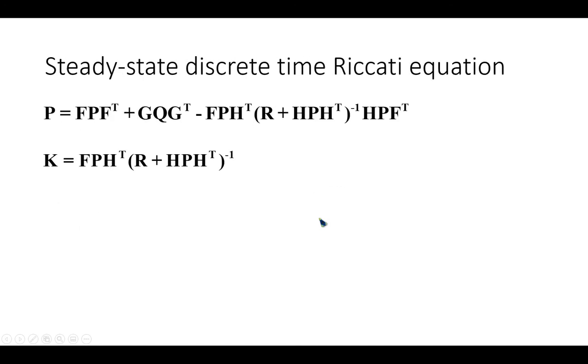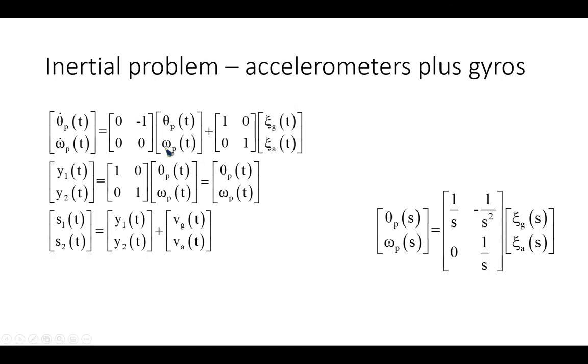Just skip forward again. And these are the continuous time equations which link, this is angular velocity, the derivative of angular position. P stands for the pitch, because I'm just going to look at the pitch and the roll separately. I'm not actually going to bother with the roll because the principle is exactly the same. So you need one Kalman filter for the pitch and one for the roll if you're going to do both. I'm just going to do the pitch.